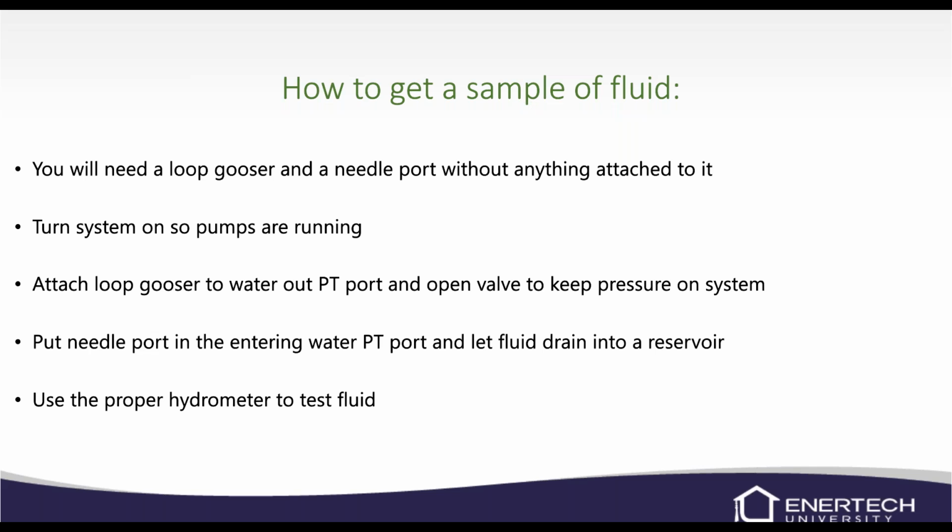If you're just curious about it, it's a Fernox test kit with some test strips. And I think it can do like 100 or 150 tests, so you can keep it on your truck. And I would always test water on a geothermal unit, always. It's easy to test, it's quick. There's instructions in the test kit that tell you how to test.